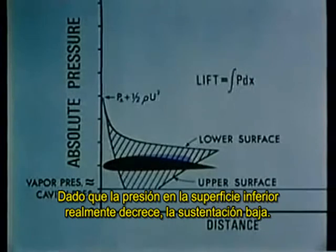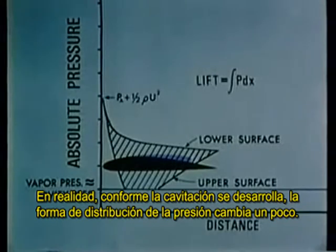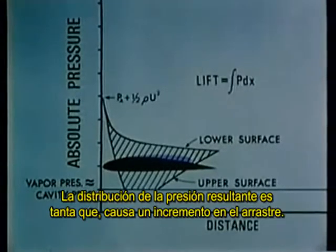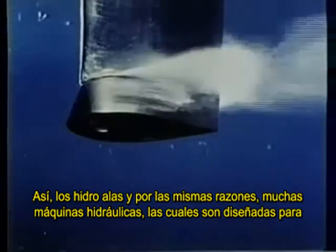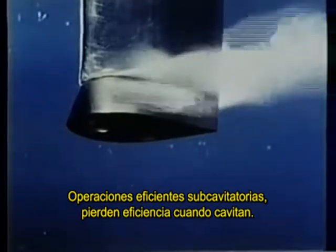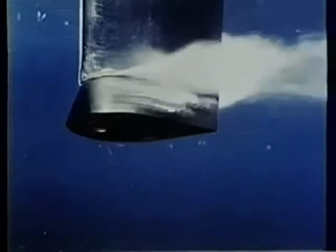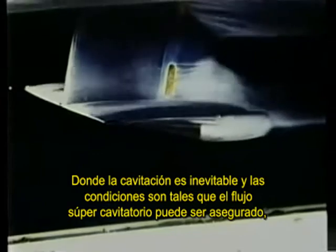Since the pressure on the lower surface does decrease, the lift drops. Actually, as cavitation develops, the shape of the pressure distribution changes somewhat. The resultant pressure distribution is such as to cause an increase in drag. Thus, hydrofoils, and for the same reasons, many hydraulic machines which are designed for efficient subcavitating operation lose efficiency when cavitating. Where cavitation is unavoidable, and conditions are such that supercavitating flow can be assured, it is possible to use supercavitating hydrofoil profiles specifically designed to achieve high lift-drag ratios.